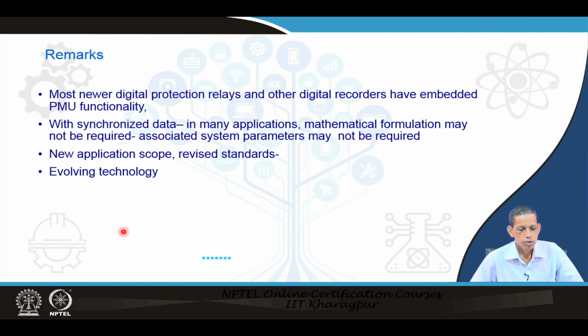Today most newer digital protection relays, protective relays and other digital recorders have embedded PMU functionality with the GPS antenna integrated. With synchronized data, many applications are possible and we have data of the systems. So, for many applications we do not require a detailed mathematical formulation of the system, no modeling, many times, because the corresponding delta angle and the corresponding phasor are being made available directly.